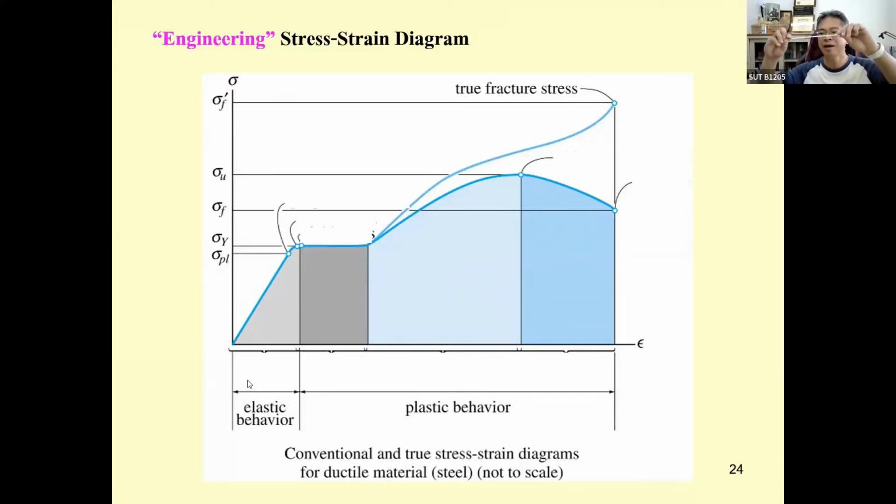Okay, so most of the time we use the material only in the elastic behavior. When you build a crane and the crane is subjected to force, the crane can deflect, but when you release the force, the crane just goes back. The same thing over here. If this one deforms and you release the force, it returns. This is elastic. And most of the time, the deformation during this kind of elastic behavior must be small. You cannot have this kind of large deformation. This is also called the failure of the structure, even though the material didn't fail.